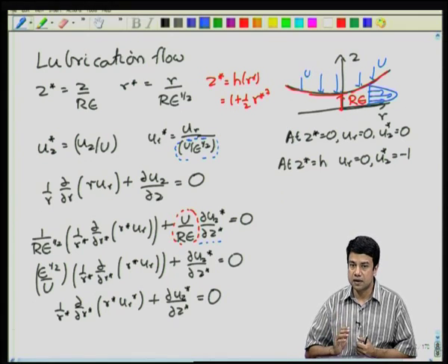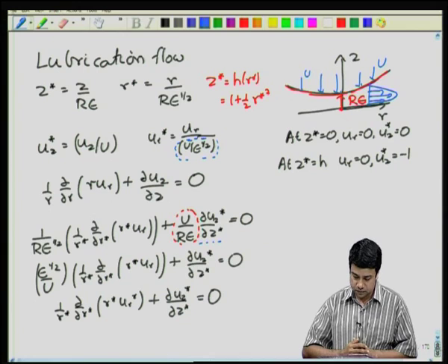Of course, at the two surfaces, the velocity has to come back down to 0, because we have a no slip condition at these two surfaces. Therefore, you have a large velocity that is coming out, which is reducing to 0 at the two surfaces, that is generating large shear stresses. And it is these stresses which are going to generate a large pressure force which resists the surfaces from coming towards each other. So, that we have scaled u r and u z from the mass conservation equation.